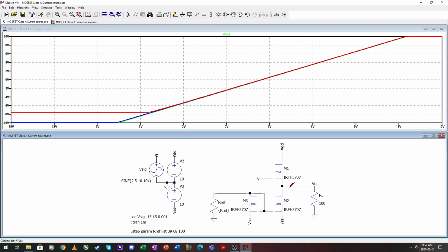Okay, there is not much to say further about Class A amplifiers. They are easy to design. They are easy to get operational, compared to some other amplifiers, but they are very inefficient. So a typical op-amp output stage would be a Class A amplifier. If you go and look at many schematics of operational amplifiers, you'll find some form of a Class A at the output.